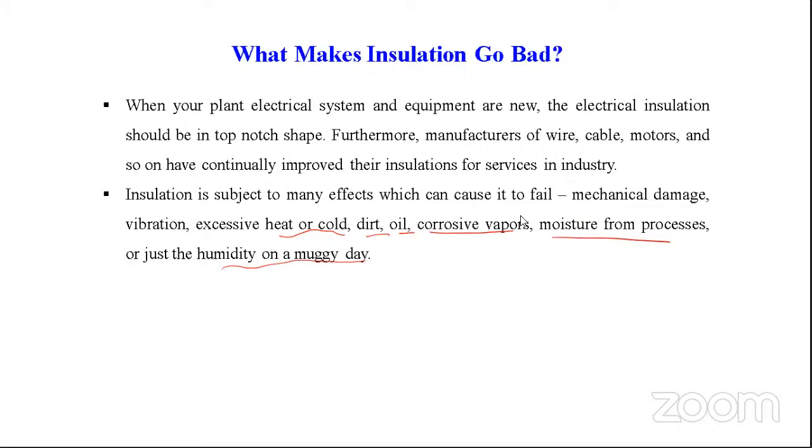Generally for 15 mega ohm, this is not a thumb rule for every equipment, because the insulating material quality depends on the voltage level. So depending upon the voltage level, we have to know what is the general insulation resistance value. But some of you have no such idea about what is the insulation resistance of that equipment.